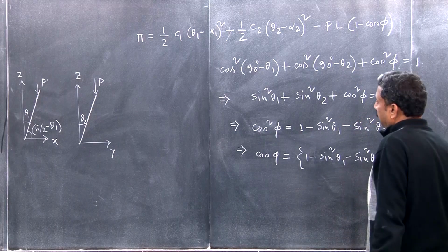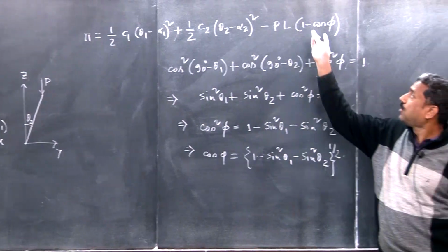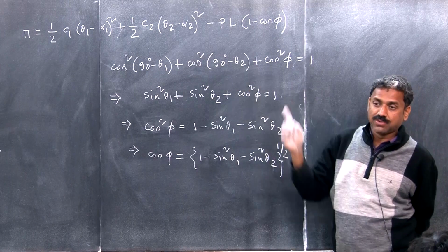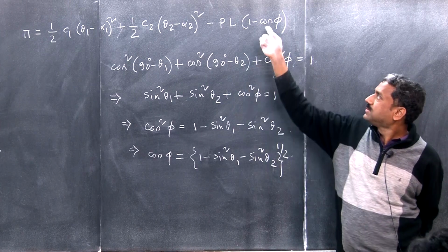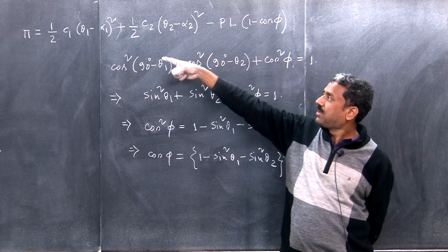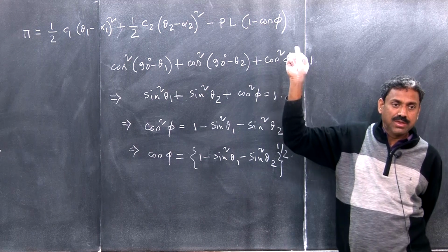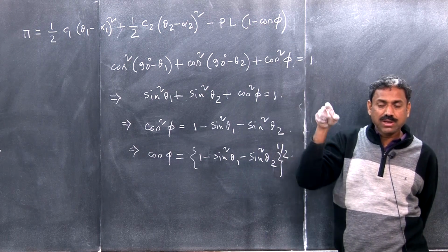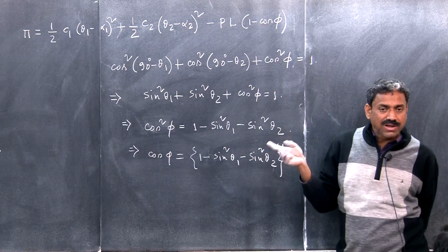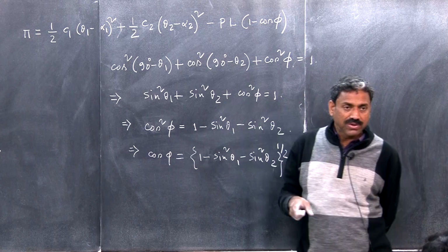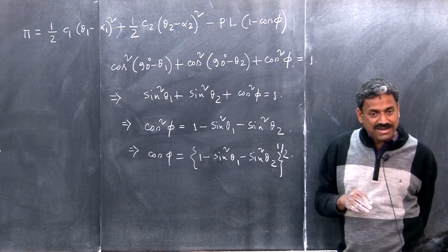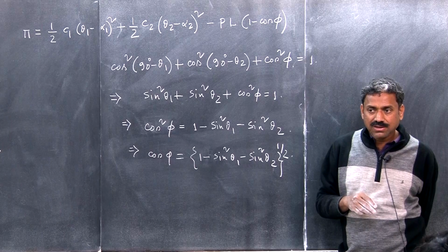So, you may wonder why I am not including cos alpha 1, cos alpha 2. Why are we not including them? Because if you see here, alpha 1 and alpha 2 appear directly. So, cos will inherently involve 1 minus alpha 1 square by 2. So, the square or quadratic term we are neglecting compared to alpha. So, the influence of imperfections in these terms can be neglected. You understand what I am trying to tell you, right?